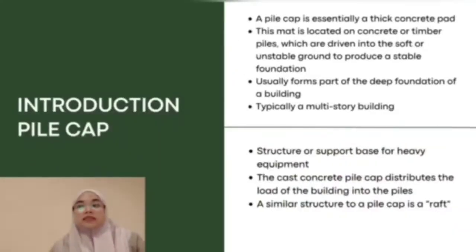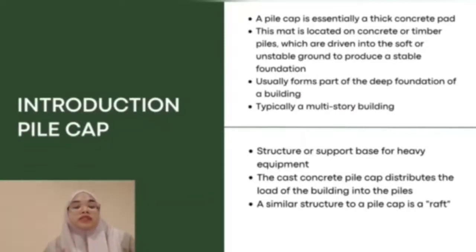The next one is introduction about the pile cap. A pile cap is essentially a thick concrete pad, and this mat is located on concrete or timber piles which are driven into the soft or unstable ground to produce a stable foundation. Usually it forms part of the deep foundation of a building, and typically a multi-storey building. And this pile cap is a structure or support base for heavy equipment. The concrete pile cap distributes the load of the building into the piles.